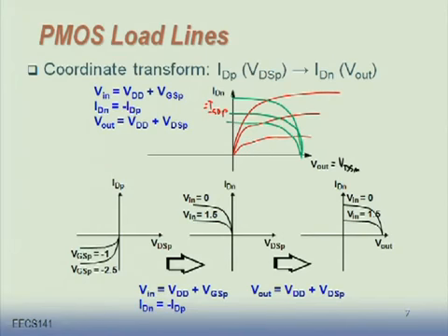Okay, and this is what essentially we have done here. We have taken ID versus VDS curves, which are supposed to be exact mirror images, reflected mirror images, symmetrical with respect to the coordinate origin. To the NMOS ones, we have substituted the axis IDP with IDN, and then shifted the whole thing to the right by the amount of VDD, and got the same curve. Everybody clear how we drew this in there?